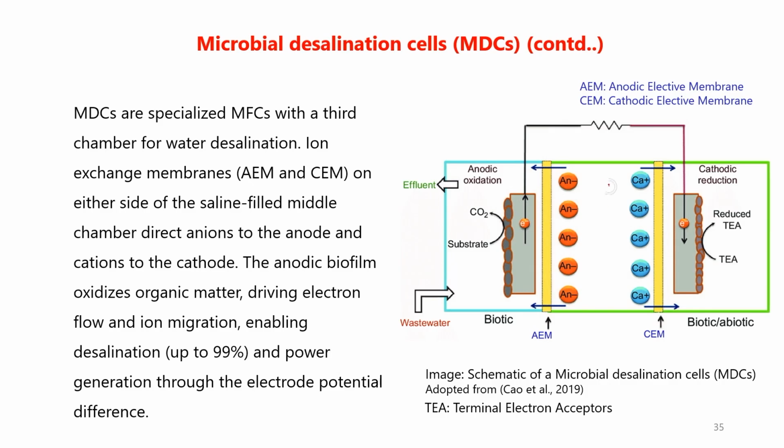So, here we have the saline water in this middle chamber. The anodic biofilm oxidizes organic matter, driving electron flow and ion migration, enabling desalination up to 99% and power generation through the electrode potential difference.